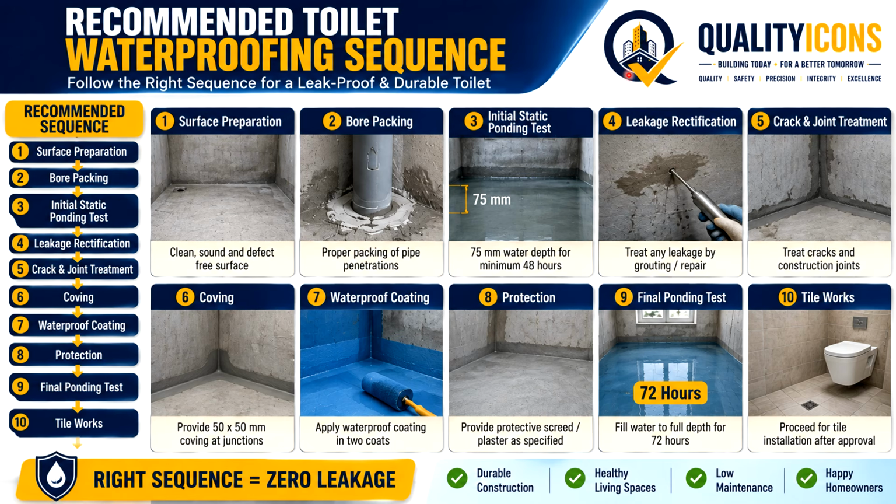Recommended toilet waterproofing sequence. This is the most important slide. This slide shows the most important part of the entire presentation, the correct sequence procedure for the waterproofing system. First, surface preparation. Second, complete the bore packing and pipe penetration treatment. See this bore packing and penetration treatment.